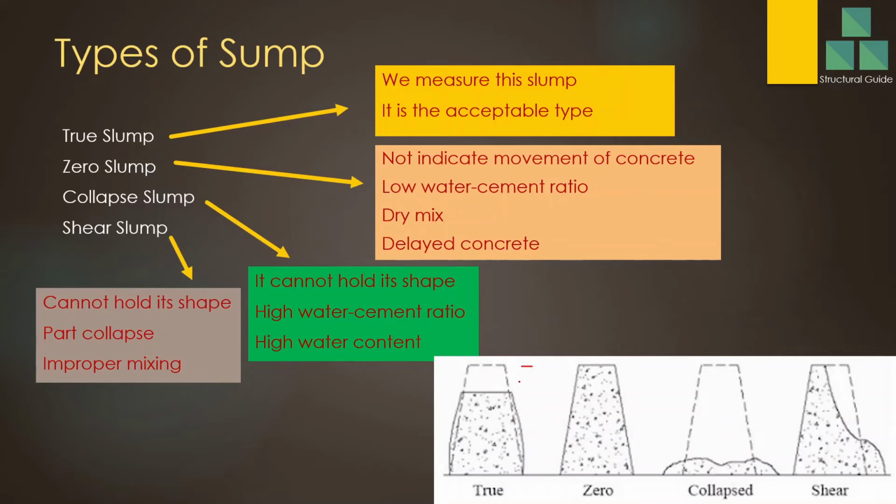This is the original slab, this is the height. So if this height is within the specified limit, then we are okay. Now I just want to mention this specified limit. Generally, these limits may be around 25, or sometimes 50 millimeters.